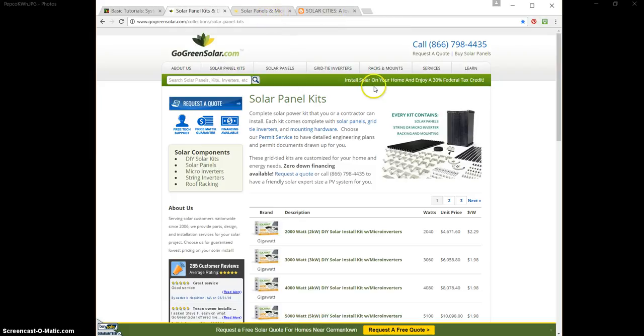So where was I? Yeah, so you can get these kits, or you can buy individual parts. It might be cheaper. Just be careful when you buy these kits or parts, that if you're not connected to the grid, do not buy grid tie inverters. Grid tie inverters are only used if you connect to the grid. Most companies provide grid tie inverters because it's illegal in most states to be off the grid. So there is a bigger demand for grid tie inverters.